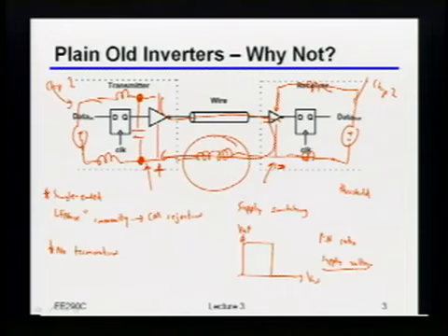It's still distributed, but nonetheless, what's the impedance between two chips that are 36 inches apart? Nothing to say that those two grounds are actually very tightly tied to each other, right? Because all it takes is for me to pull some current around over here that goes through some other ground return paths that have nothing to do with this signal, and I'm moving around all over the place, right?